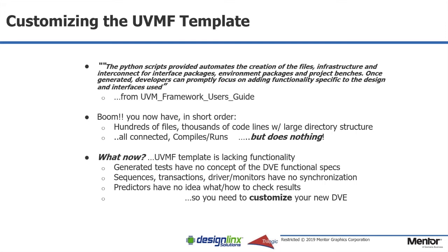So what do you do now? Your UVMF template is lacking functionality. Your generated tests have no concept of the DVE functional spec. Your sequences, transactions, drivers, monitors, agents have no synchronization. Your predictors have no idea what or how to check results. So you need to customize your new DVE.